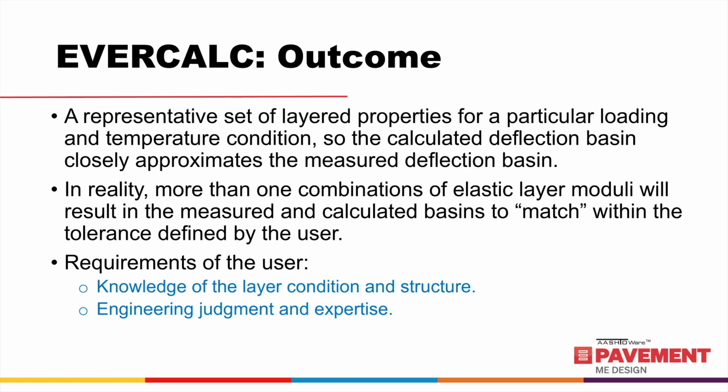Although, in reality, depending on the tolerance allowed in the procedure and the relative number of layers compared to the number of deflection sensors, several combinations of moduli may cause the two basins to match reasonably well. The more the user knows about the pavement and its simulation, the better the results. Two important requirements by the user are knowledge of the layer condition and structure, and a close approximation of the layer thickness. Engineering judgment and expertise is required accordingly, because back calculation is both a science and an art.